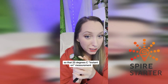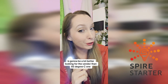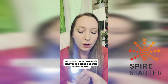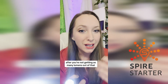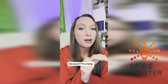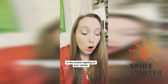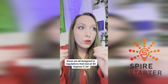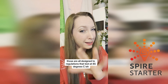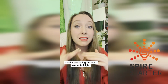So that 25 degrees C instant-on measurement is going to look a lot better for the vendor than the 85 degrees C one, even though in most applications you want to know how much light you're getting out after it's warmed up, after you're not getting as many lumens out of that. Most applications are going to care about that 85 degrees C number, because if it's a lamp, a luminaire, a light for your house, a restaurant, an office, the parking lot, or the exterior lighting on your vehicle, those are all designed to regulations that test at 85 degrees C-ish, wherever thermal stability is. So after it's warmed up and it's producing the least amount of light.